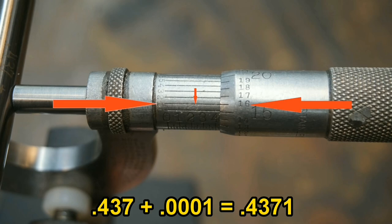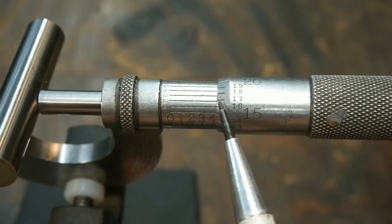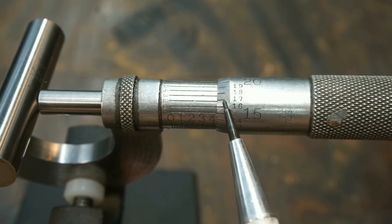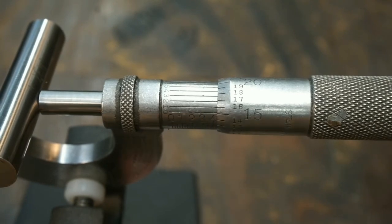So that's how you split 1/1000ths of an inch, is lining up whichever one of these lines, 0, 1 through 9, is perfectly in line with one of these numbers on the rotating barrel. That's what you add to your figure that you come up with.